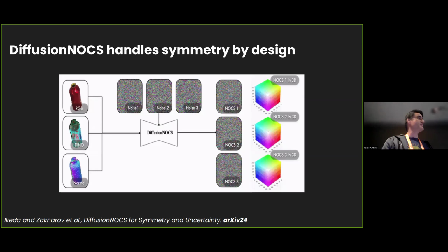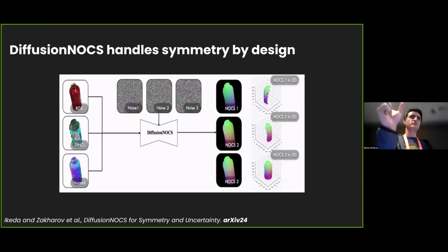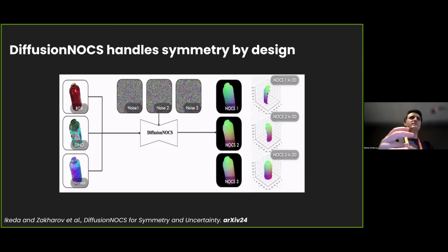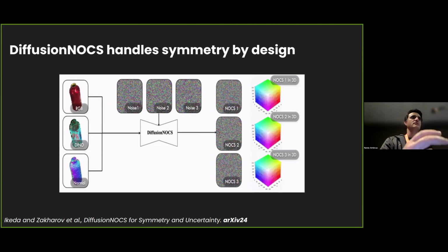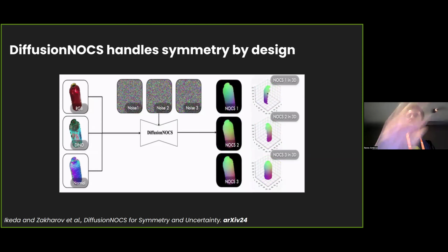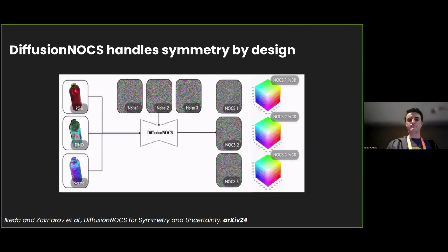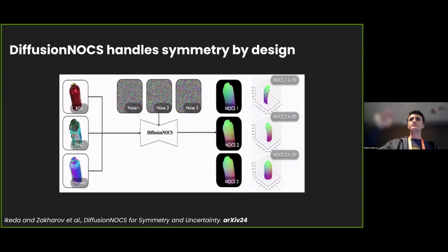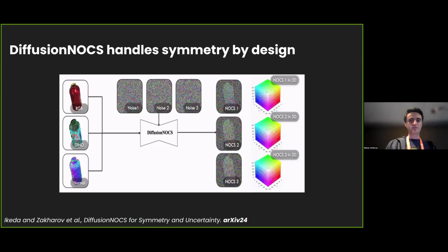And because we have the confidence, we can select the highest confidence pose. Or if there are multiple poses that are high confidence, we can select the one which has the best kinematic constraints. So if in some cases the arm goes like this, it might bump into something, so we select the other pose, which improves the results quite a bit. And we have ablations on this in the paper.